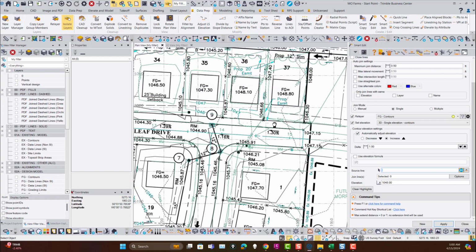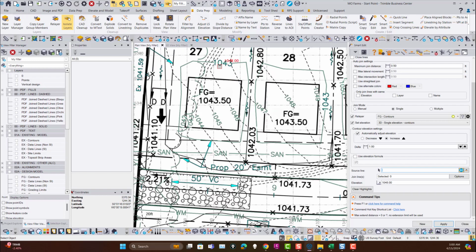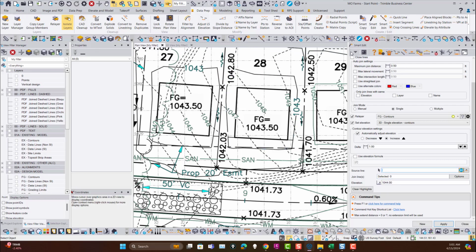And then we're up and amongst the contours up the top here, so we'll start at this end again. So this is 1043, so Shift X to call up the contour 1043, enter. So we're going to click on this one and enter, Z, click on the line and enter.